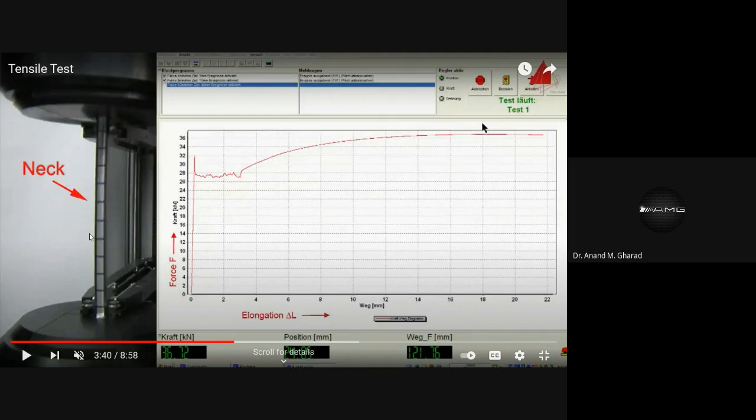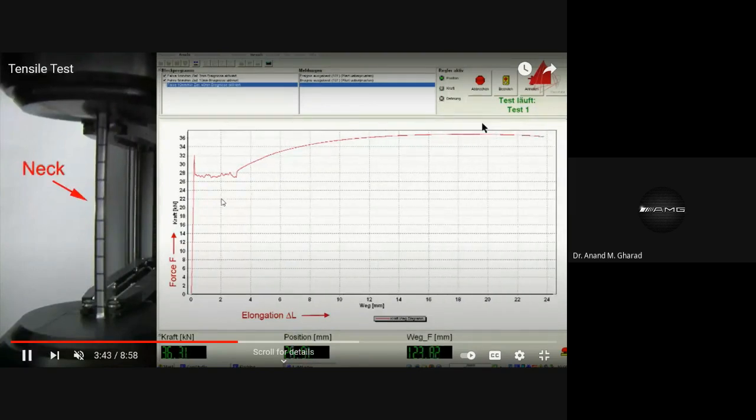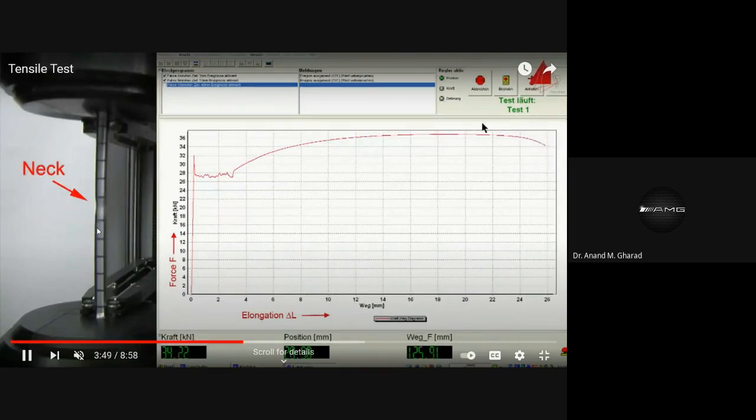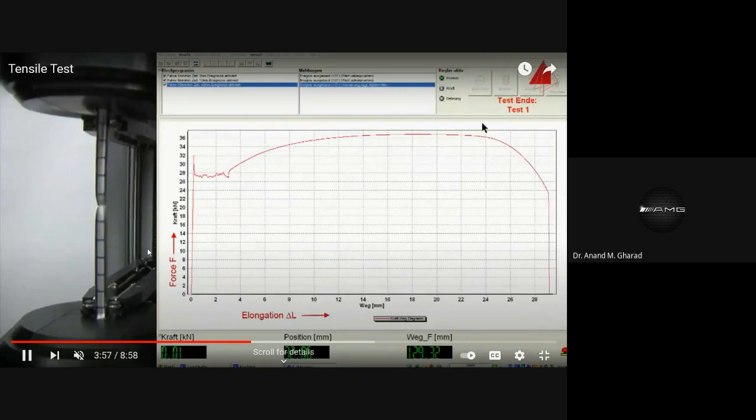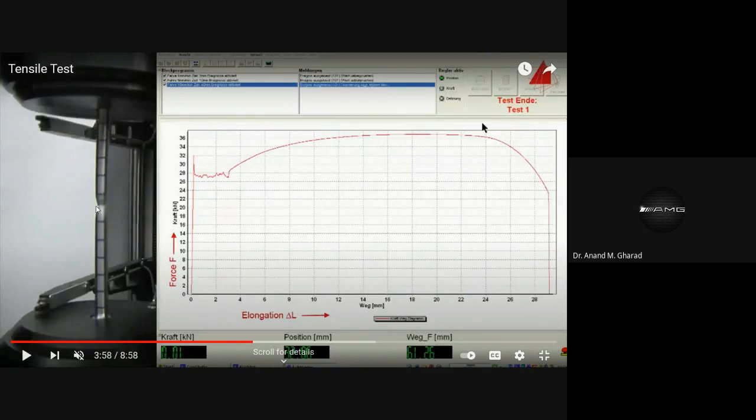Necking means the overall cross section of that portion reduces, and you will observe the typical location to be somewhere at the middle of that specimen. Fine. Then it increases. Just observe the left side specimen part, you will find the cross section is changing, and the force is getting reduced, and a point will come that this specimen will break. You can see it failed.